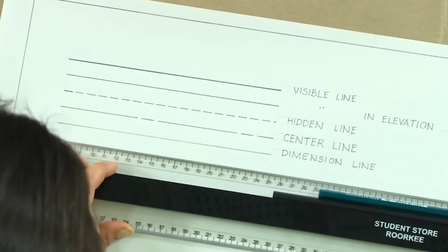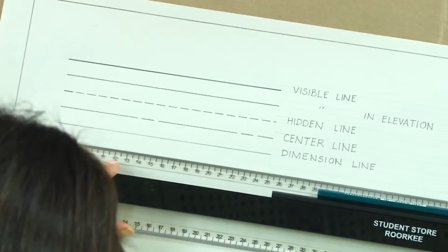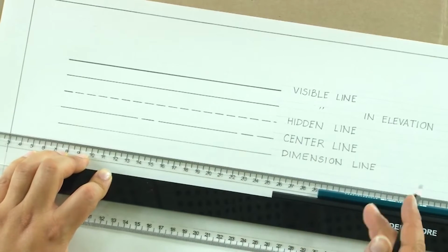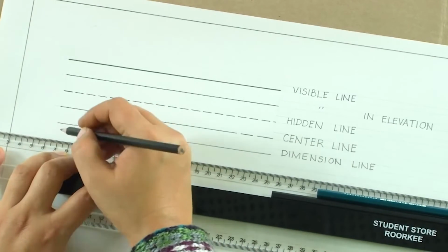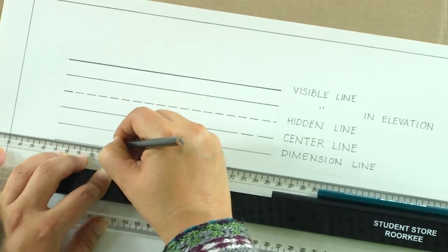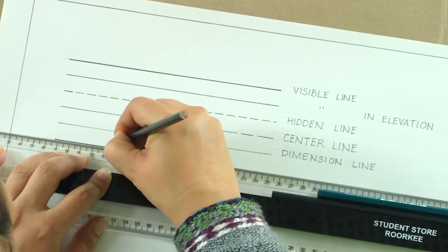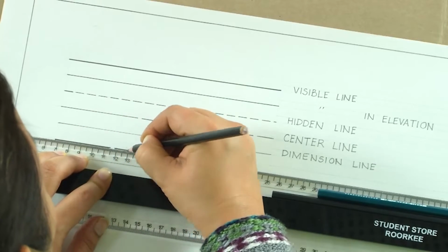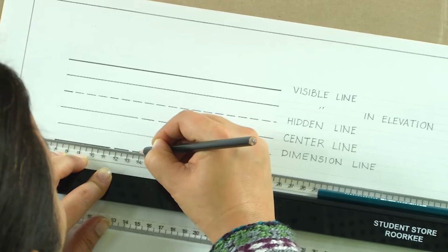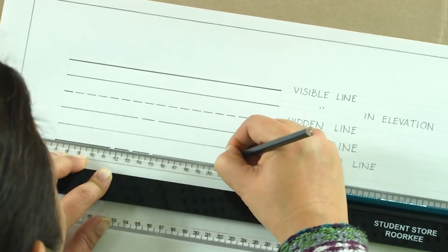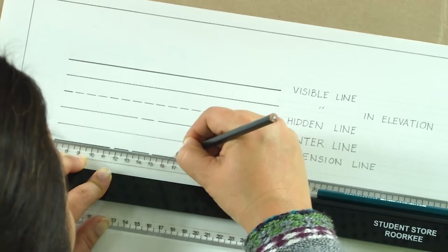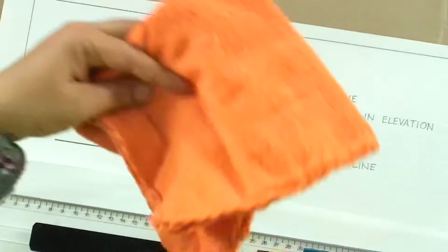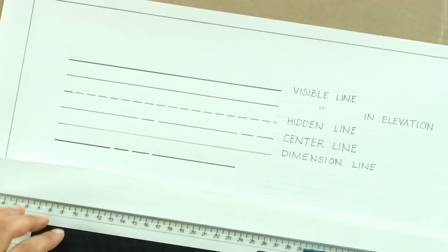Next, we have a section plane line. A section plane line is a very thick line and which is also called a cutting plane. So, what we have in this one is a very thick line, a bigger dash, then two smaller dashes. It is very similar to center line, but this is what we use for the cutting plane line.